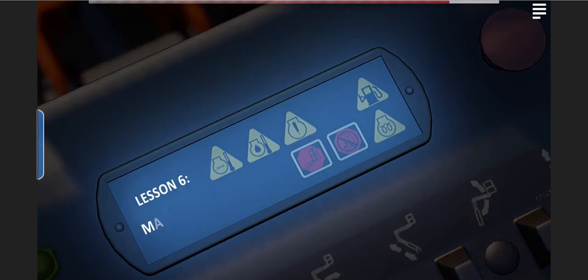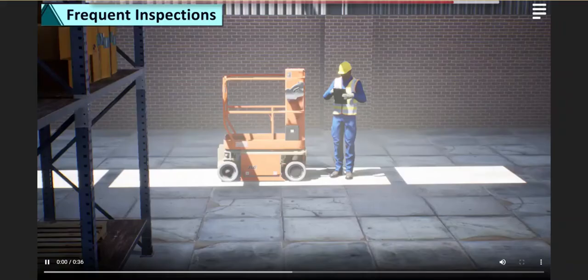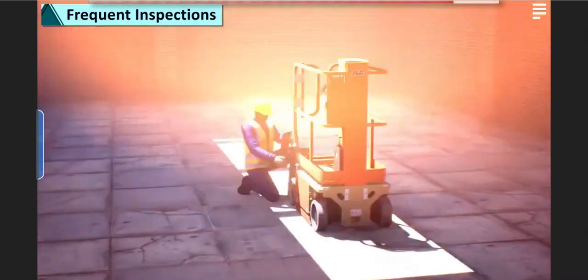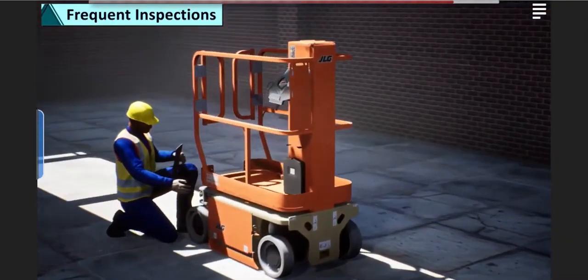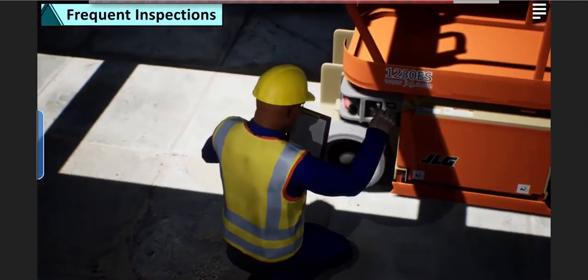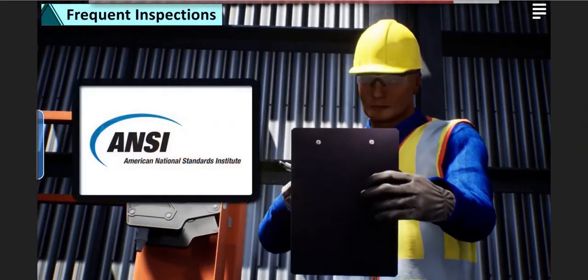Lesson 6. Maintenance and repairs. Frequent inspections are more thorough than pre-start inspections. They involve a complete and careful inspection of all parts, functions, and controls on the MEWP, including all items specified by ANSI and by the MEWP manufacturer.